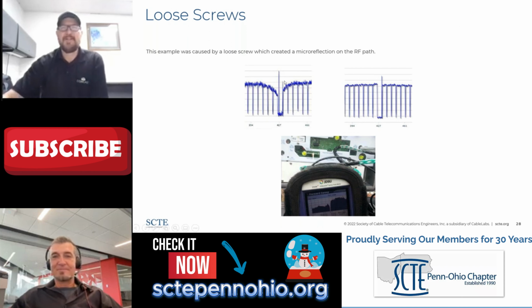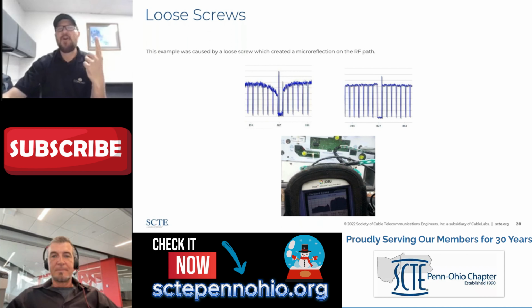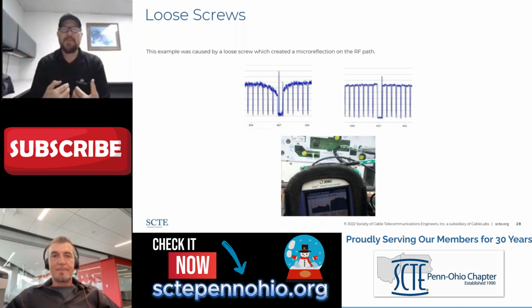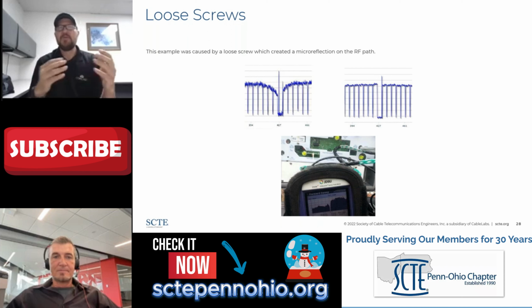When we talked about what channels are represented in this full band capture, you can see this CW carrier at 429 megahertz. That's our ALC pilot. So knowing where your ALCs are and whether they're analog or digital can influence the priority that you put on that suckout. Not that the suckout itself isn't important, right? But if those were just linear video channels in there, it may cause some tiling problems on a customer set-top box if they're tuned to that particular QAM.